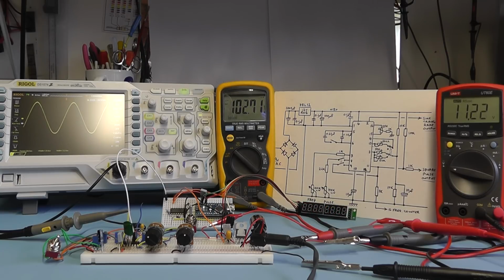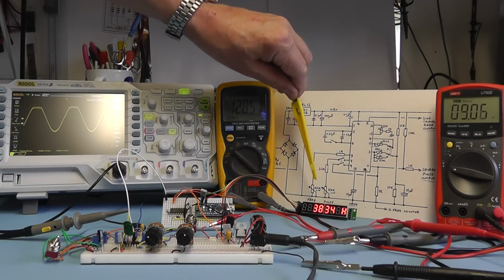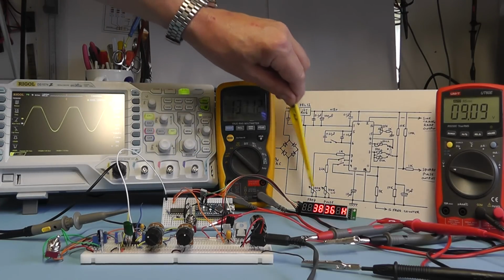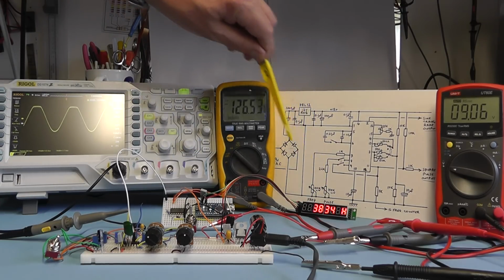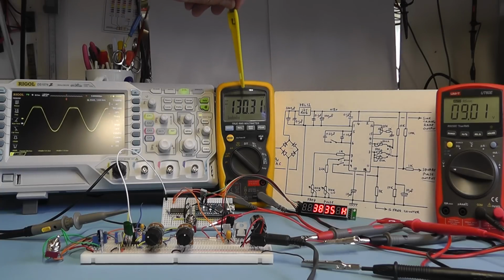Oops. Right, I switched on the power. You can see the Nano is working, and you can see that the display there is giving the frequency readout correctly, but unfortunately when we look at the display of the waveform there, you can see that there is some clipping and noise on the top of the sine wave, so clearly something's not right. The current now being drawn is 130 milliamps. That's probably the reason why we have an issue here.